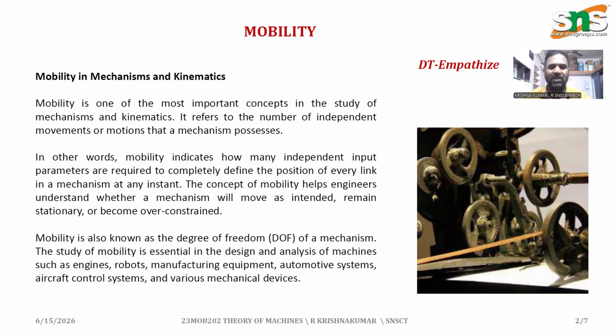Mobility is one of the most important concepts in the study of mechanism and kinematics. It refers to the number of independent movements or motions in a mechanical process. In other words, mobility indicates how many independent input parameters are required to completely define the position of every link in a mechanism at any instant.